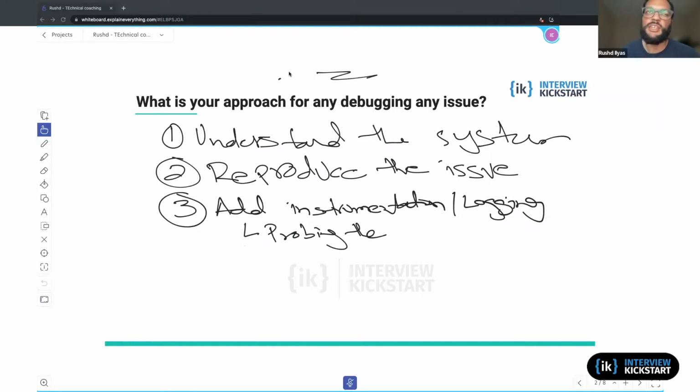It could mean anything, right? It could mean adding a digital multimeter. It could mean adding a scope on it. It could also mean adding a protocol analyzer. Because once you know that you can reproduce the issue, now you want to dive into it, to see at what step it's failing. So having that information helps a lot.